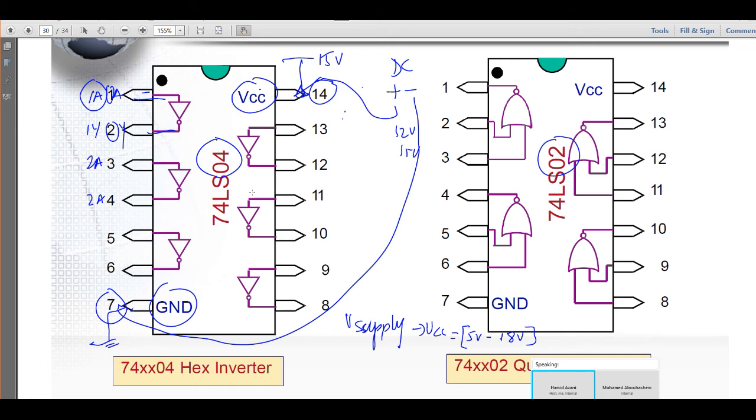So this will also come by experience. As soon as you work with them, you can understand how you can use them. But now, for all experiments, be sure that any circuit you wire on your breadboard, you feed it first. You should give it plus and minus 15 volts, for example, before you use the gates from that chip.